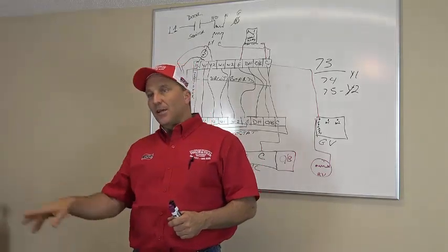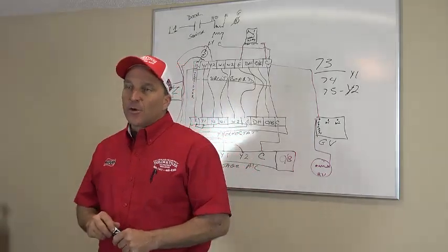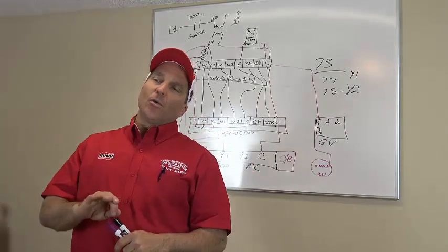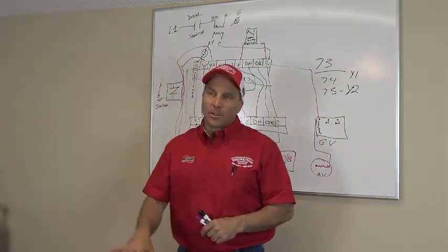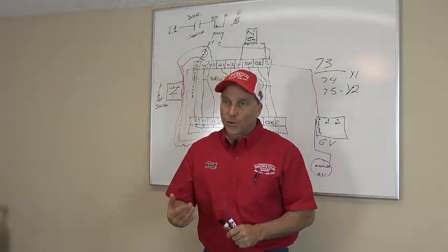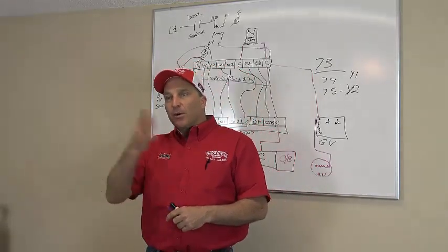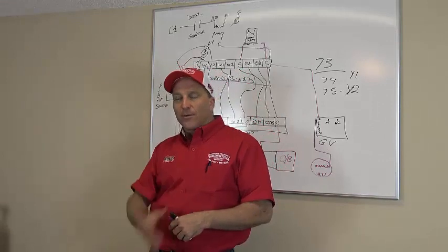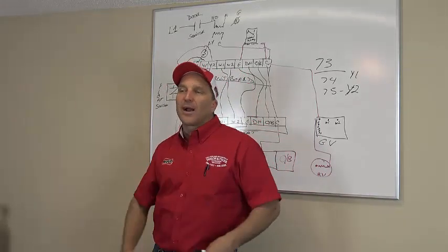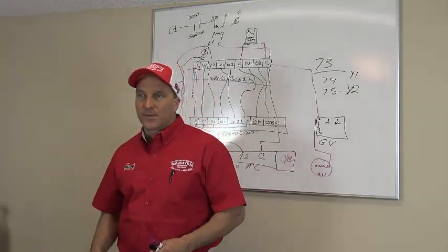Okay. So let's say you put that on low. So if you energize G only, G only gives you a lower blower speed, and that is used for filtration. So if you run a low fan speed on filtration, it circulates airflow through, right? And you filter your air in your house. That's what that's for. Okay?